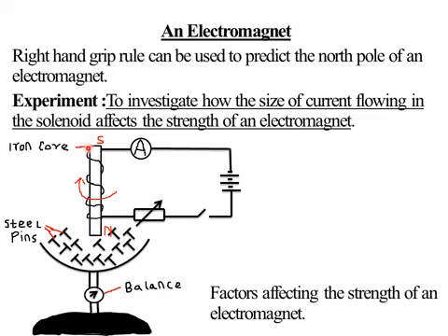Then after that, connect it to the battery as shown here. After winding it, of course we connect it to the battery. This is our battery here. After that, you switch on the current and adjust the variable resistor, or the rheostat, to give a current of maybe around 0.5. So after connecting, we close the switch, then we vary our rheostat. Remember, the rheostat will determine the amount of current passing through the circuit. So maybe we set a small current of maybe around 0.5 amperes.